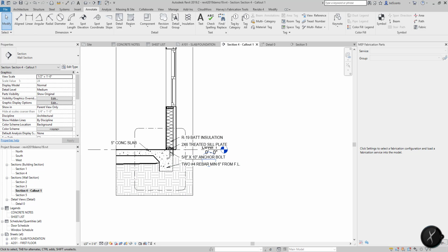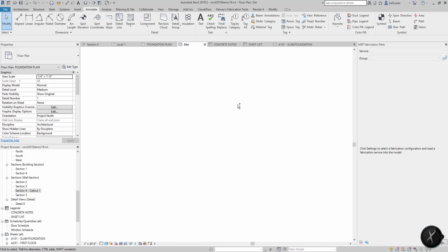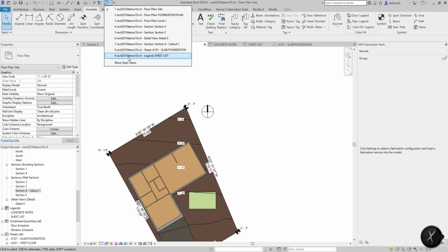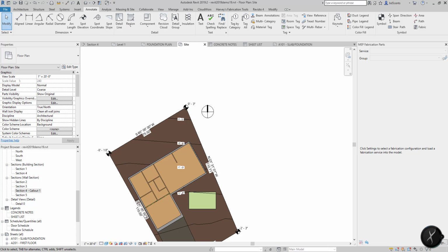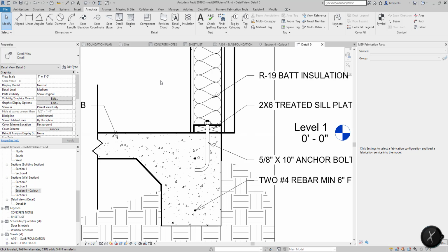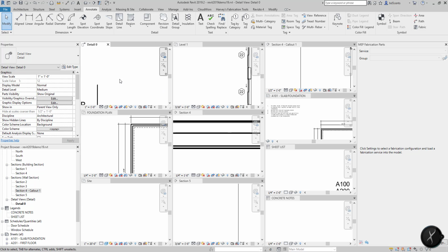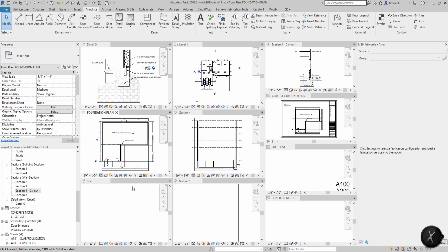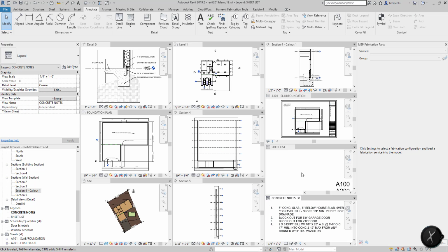So let's see all the drawings you've created. We're going to hit Control Tab and cycle through. So we've done quite a few. We've done a lot, actually. 9 total views for this lecture. Window tile will display all the drawings on the screen. So if you hit WT, we'll do that from this drop down here, we can find that detail, and we'll hit WT, and you can see all the views that we've created. You can middle mouse button in the center of these as well, and it'll view extents them. So I'm middle mousing in the center, just viewing all of what I've done.